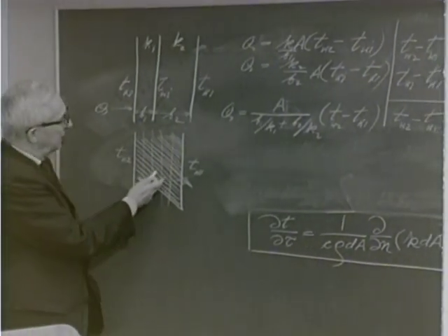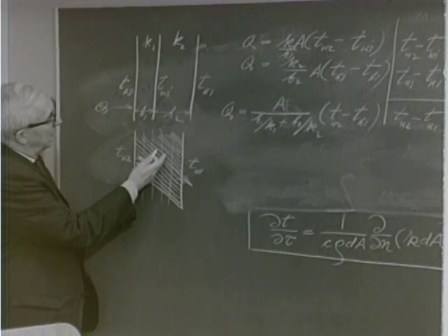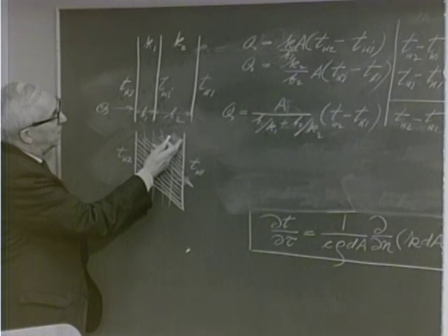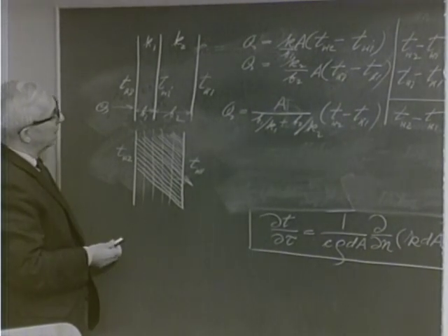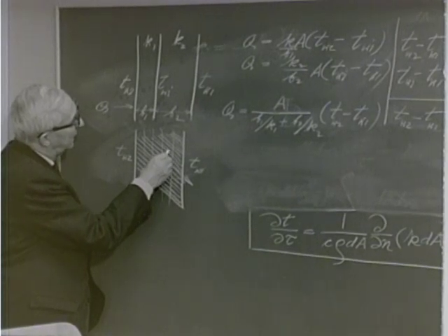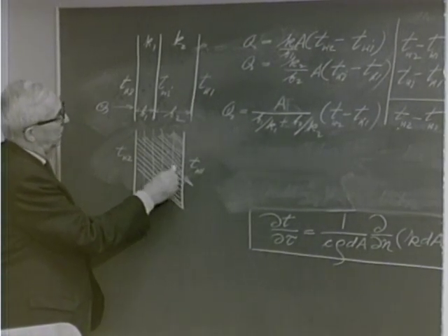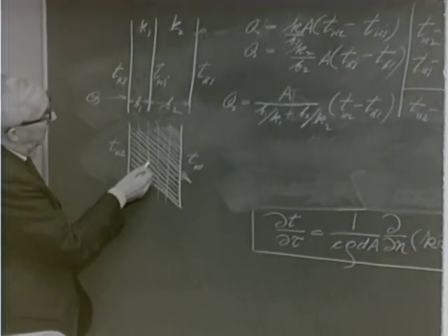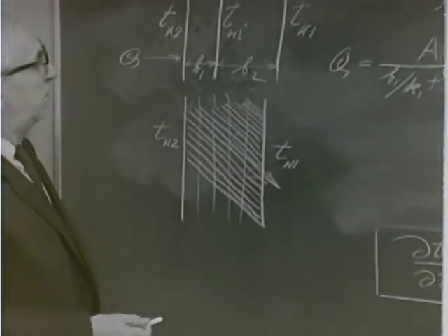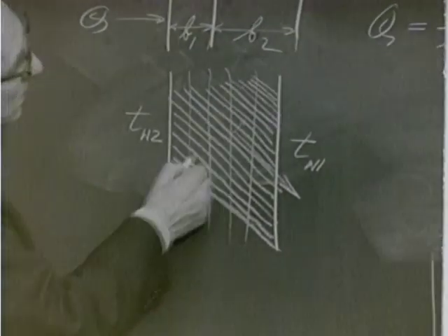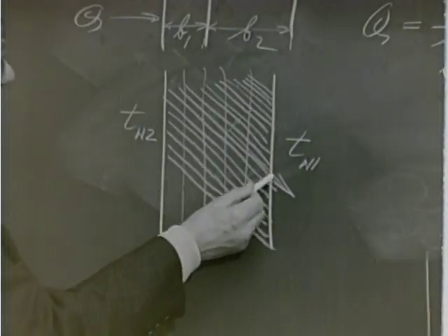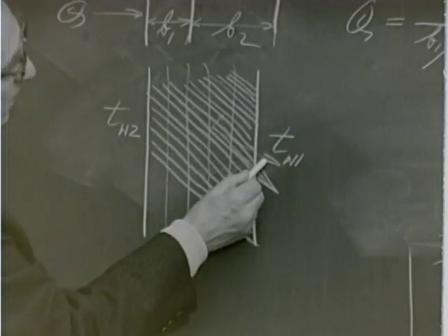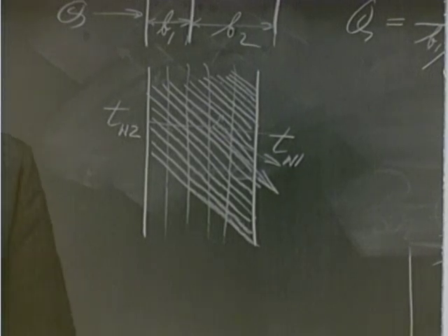Of course, if we have gone here to the extreme, if the situation would be metal, plastic, metal, plastic, this means good thermal conductivity, poor thermal conductivity. Still, obviously, the thermal conductivity in this direction would be smaller than in this direction, because the heat can readily flow down the metal strips, whereas here it always has to cross through poorly conducting material. But there is a certain conductivity in this direction too, and we would find that the heat flux doesn't go parallel to the lamination, but in some other direction. But still, it wouldn't be in the direction normal to the wall.